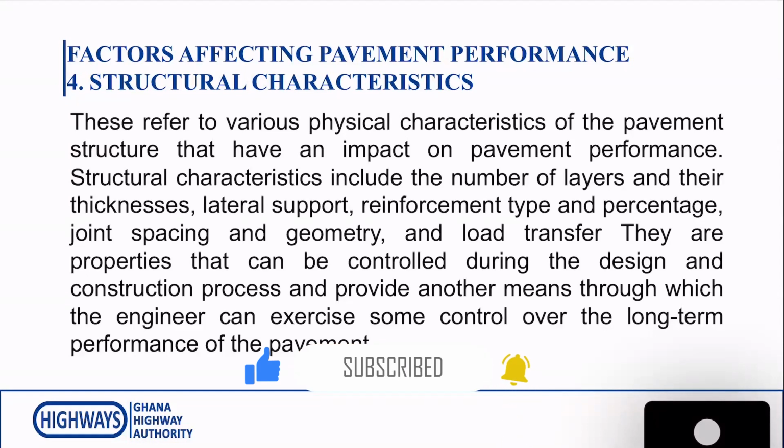Also, it includes lateral support, reinforcement type if it's a concrete pavement, joint spacing and geometry, as well as load transfer. Now, these are properties that can be controlled during the design and construction process, and they provide another means through which the engineer can exercise some control over the long-term performance.